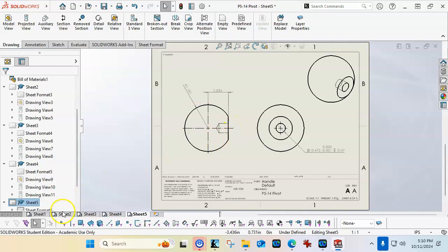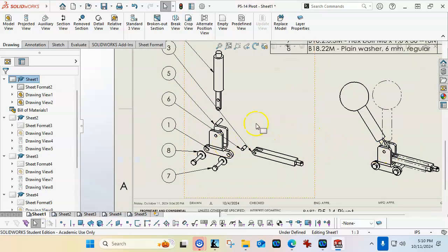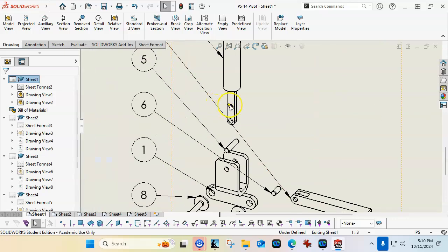Now, what we don't have in here is, since this is going to rotate, do we need a bushing? How much load and force is this actuating that we might want to make this a little bit bigger, press a bushing in, and have a bronze bushing right on a steel or a stainless steel on the stainless steel pin?